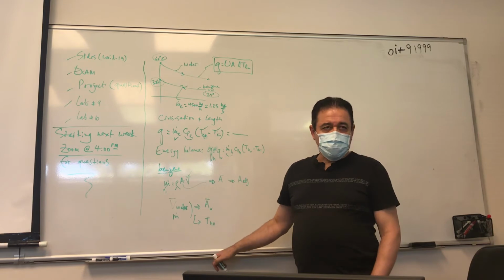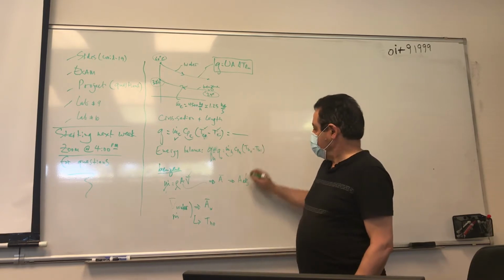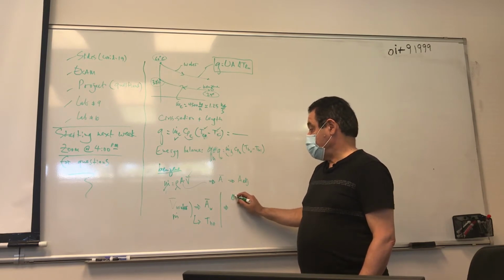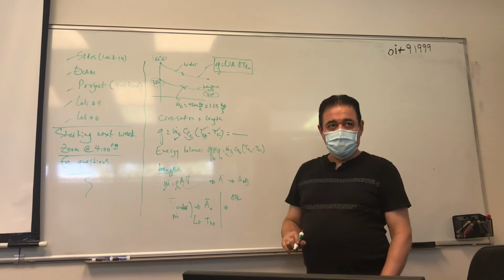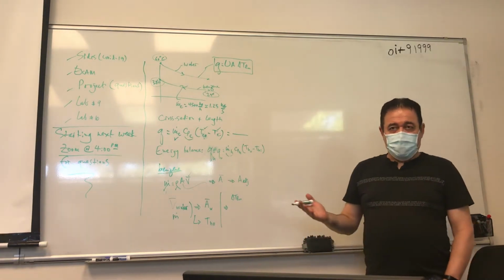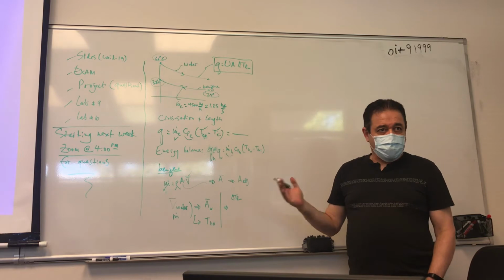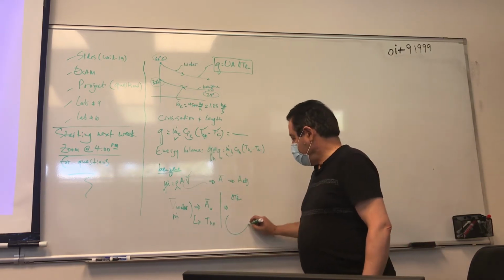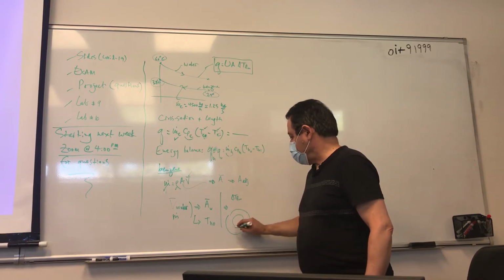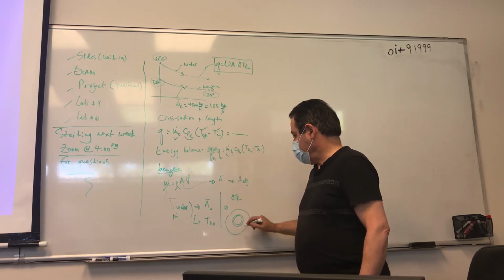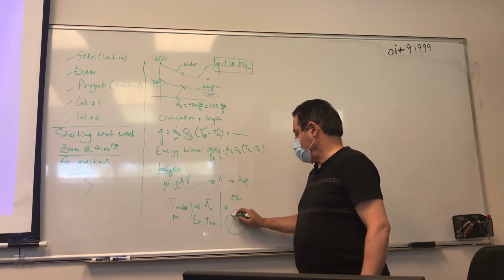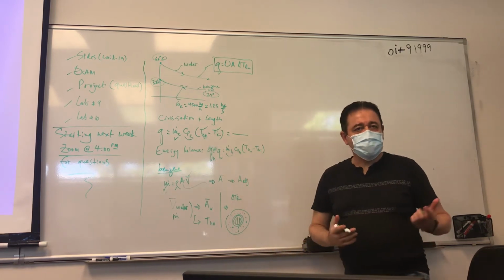Once you find the temperature of the hot water out, what can you find afterwards? The L? Well, not yet. You can find the delta T Ln, the log mean temperature difference. Now, we're still not finding our length yet, right? Because hopefully by the time you reach here, you have a cross section that's going to probably look like this, in which one fluid is flowing here and another fluid is flowing there. So what's the next step now?